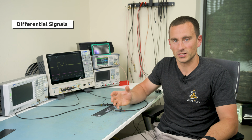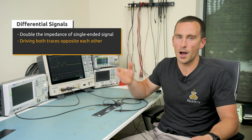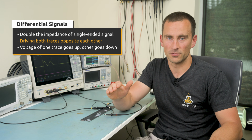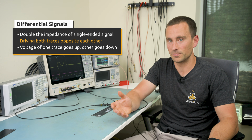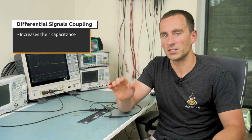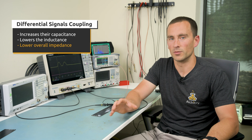The reason differential signals are double the impedance of a single-ended signal is that you're driving both traces opposite each other. When you raise the voltage of one trace by 1 volt, the other one drops by a volt. So for a swing of 2 volts, you have about the same amount of current running through them. This makes it look like twice the impedance of either single trace. However, differential signals also couple to each other. The coupling increases their capacitance and lowers their inductance. This results in a lower overall impedance.